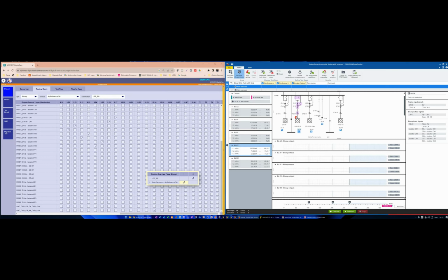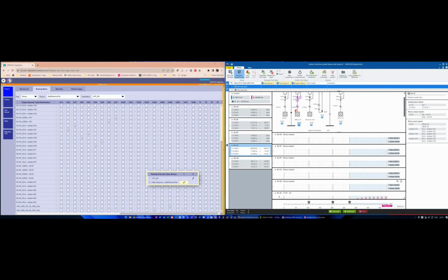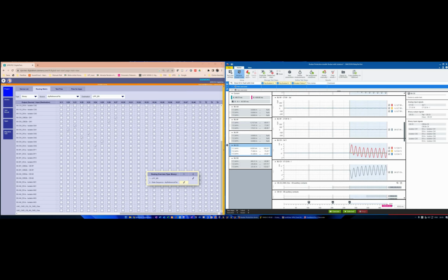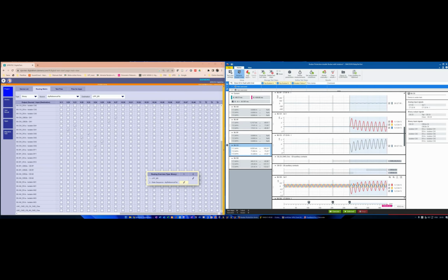The other step will be this close command. And to show all this interactivity, I will show here. In the first step, we didn't apply the fault. We apply the fault here in the second step with my bay open. And in this third step, I give the close command to my bus bar protection that I linked here.